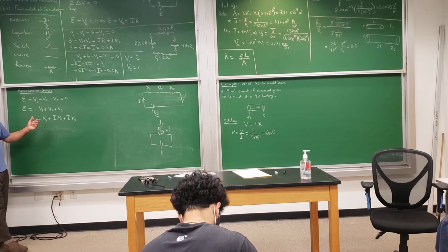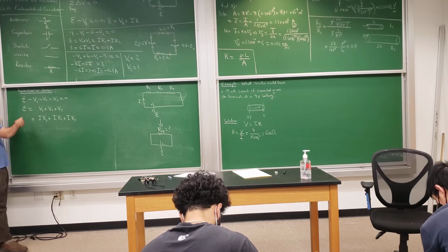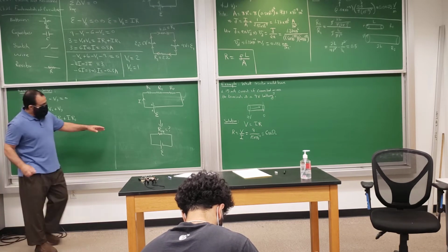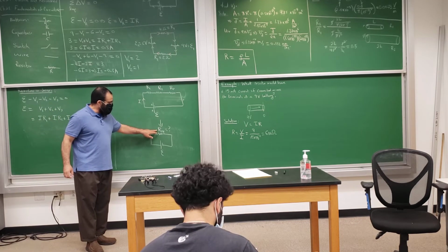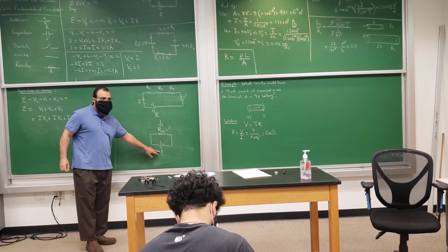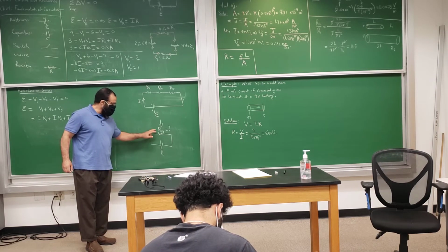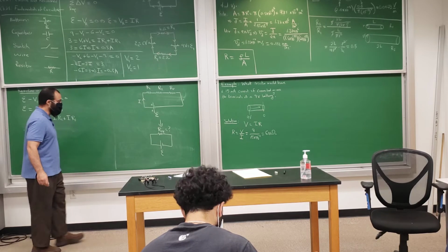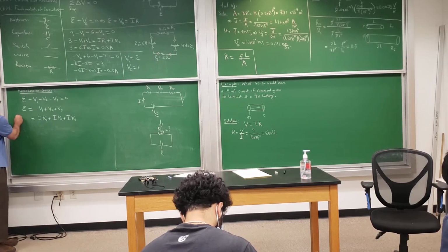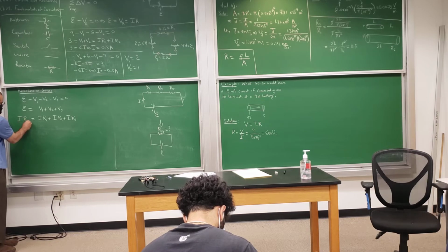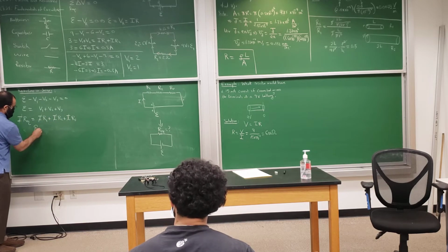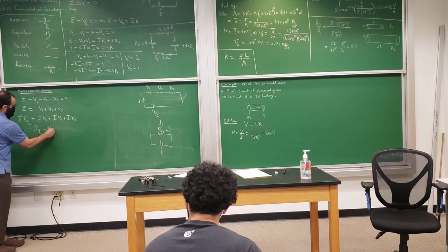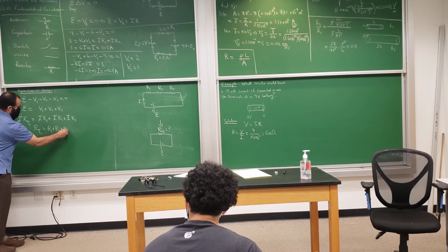It's the same current, since they are in series. Now, if I were to put their equivalent, the voltage drop across the equivalent would equal the voltage of the battery. Remember when we only had 1 resistor, it was just the EMF of the battery. So it's equal to I R equivalent. So the current cancels, this I can be divided out. So you get R equivalent equal to R1 plus R2 plus R3.